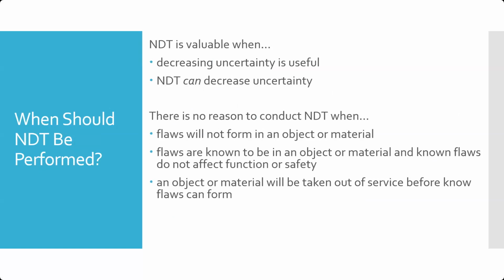And so we want to make sure we're not conducting NDT in such a way that it's going to be where flaws will not form in an object or material. So if an object or material isn't being stressed in a way that could cause flaws that would be found by NDT, or if there are already known flaws, accepted, there can be materials that sometimes have accepted levels of impurities or accepted levels of known flaws, as long as it's not affecting function or safety, that doesn't necessarily mean that part has to have NDT performed on it regularly.